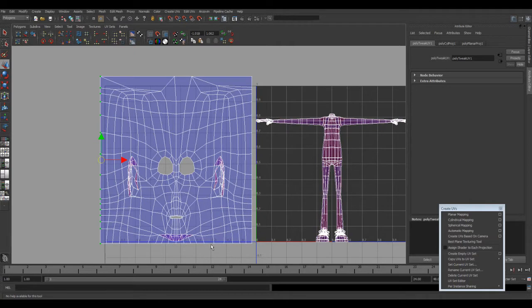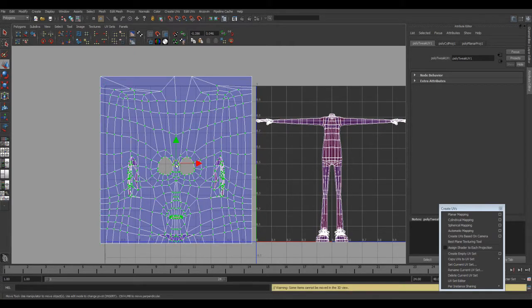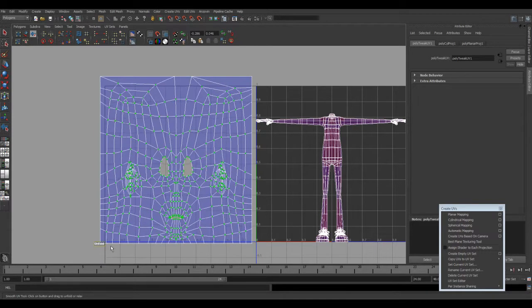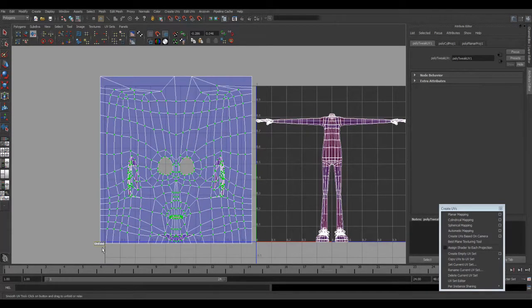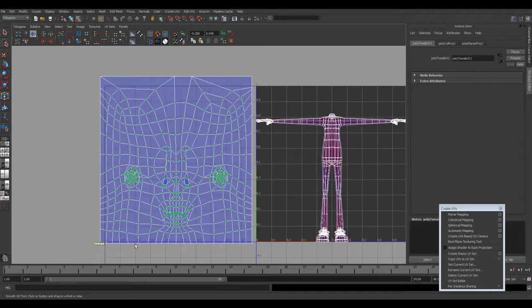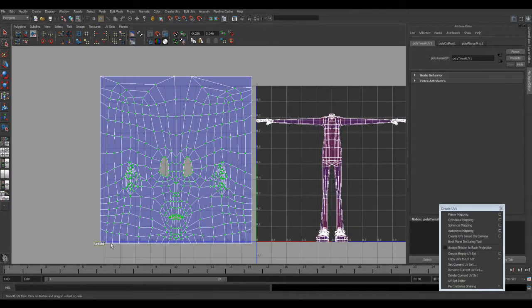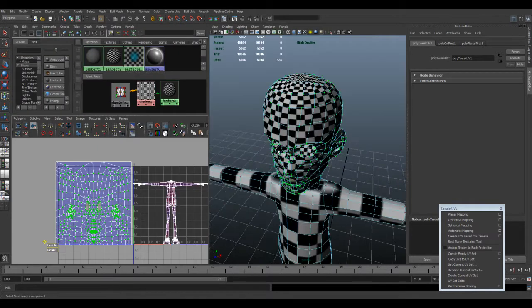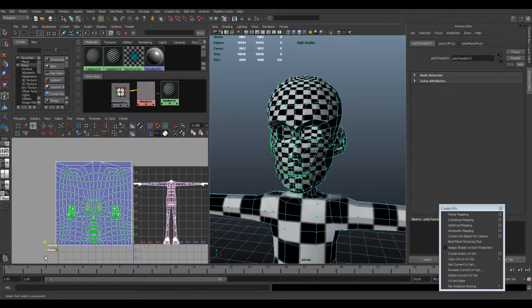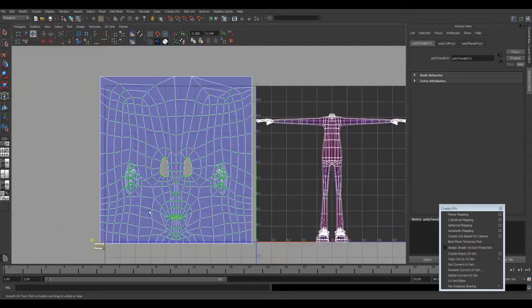Okay, right. Now there are some really useful tools in here. If I select what's inside this mesh now, there's a tool up here called the Smooth UV tool, which is very, very impressive. If I select this and move the unfold virtual slider backwards and forwards, what's happening is it's using an algorithm to spread this texture out. If I come back into my face, I'll show you what's going on here. You can see it's enabling me to spread out these UVs.